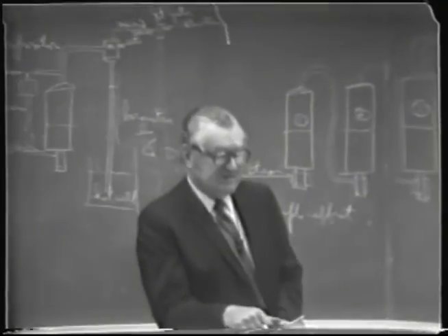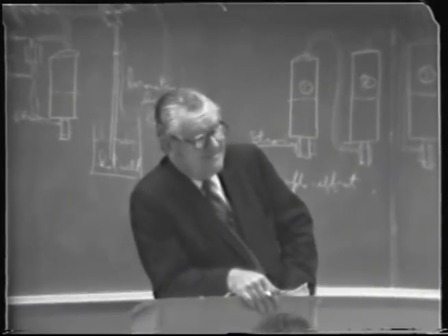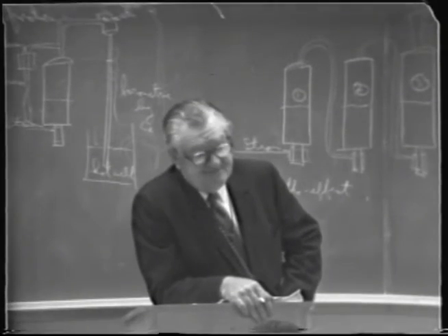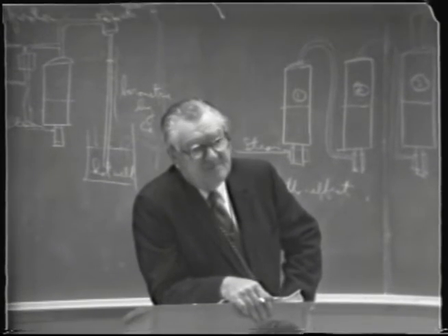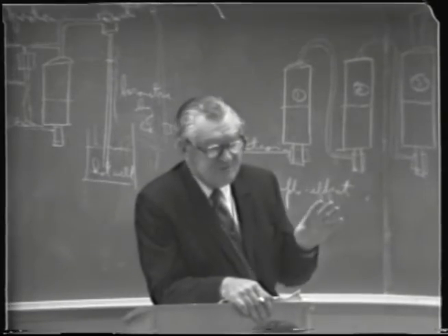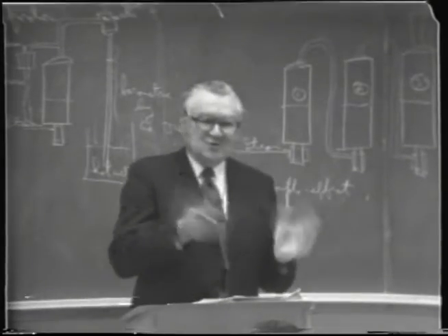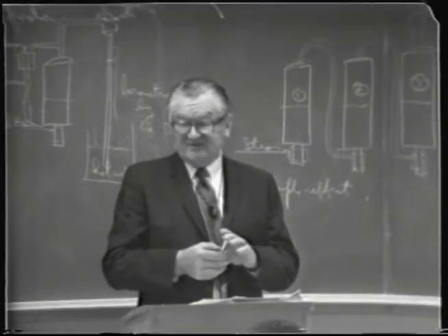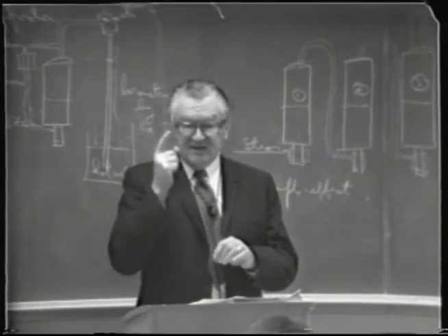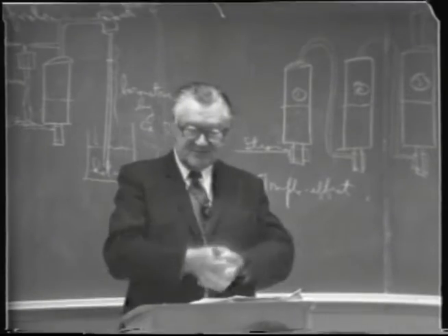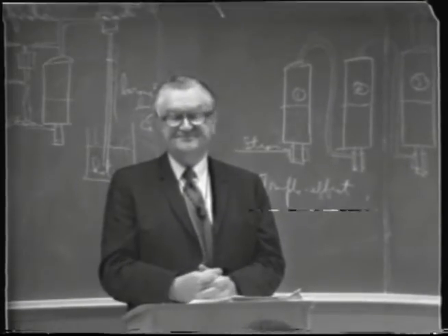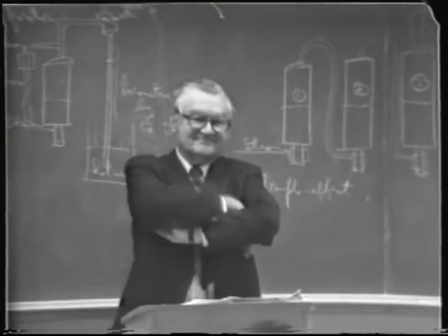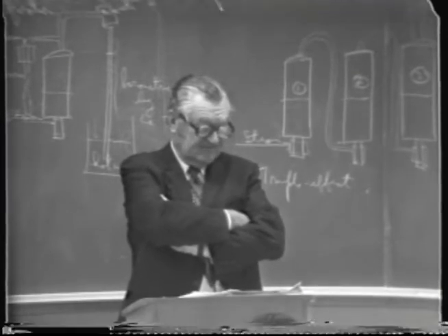Because the heat of vaporization of water, that is of steam, is around 970 to 990 BTUs per pound. Depends a little on the pressure, but it's not critically dependent on the pressure. So from a practical standpoint, you tend to get 1 pound of water evaporated per pound of steam consumed in the first effect, or in a single effect.